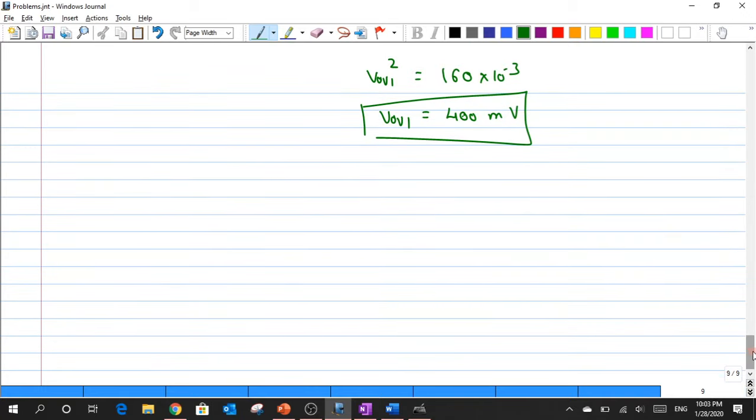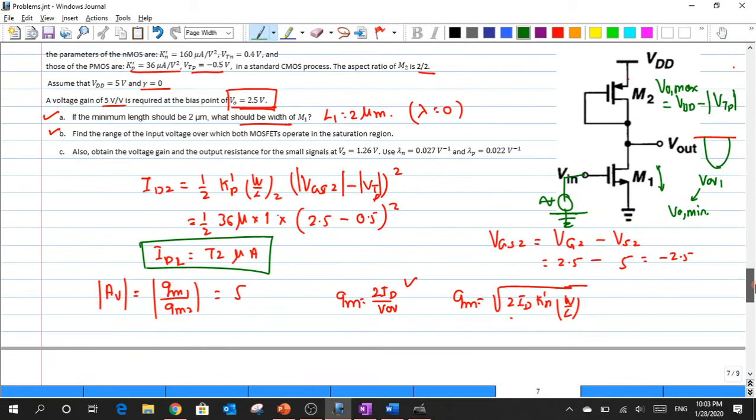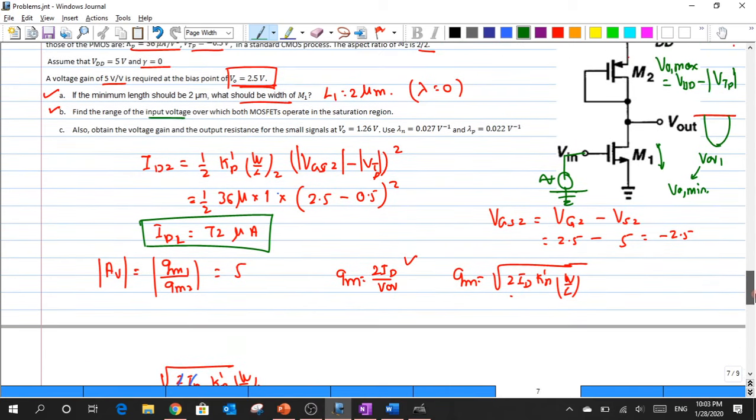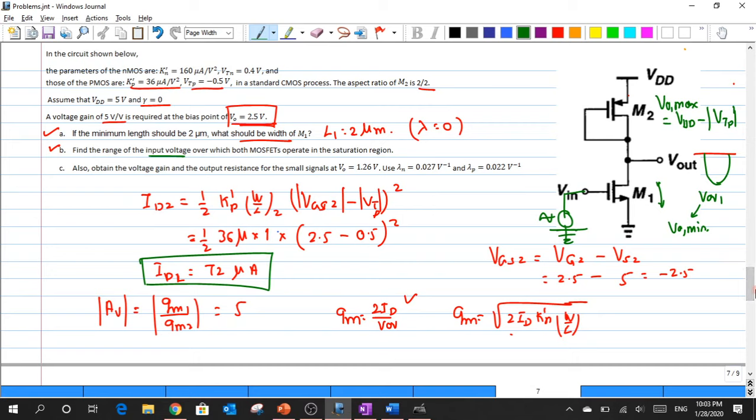The third question that has been asked, I guess, is not the output voltage range, it is the input voltage range that is being asked. So again, how will I compute that? We know that whenever there is an input swing, the minimum value that I can have across this input swing has to ensure that this transistor is never turned off.